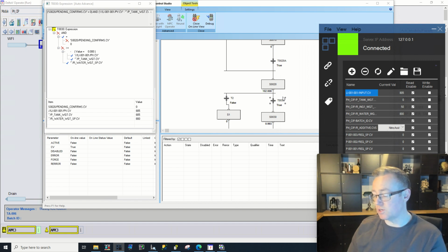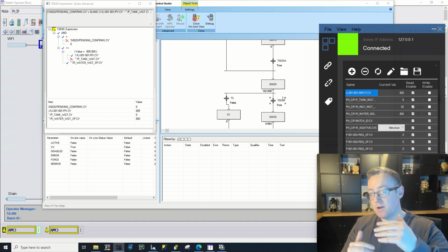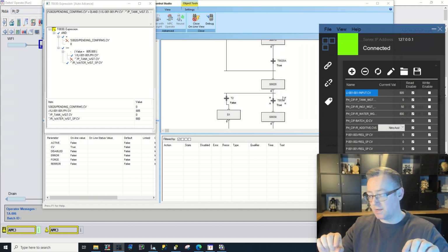And that's very much an example of how you call an equipment module from a phase, where there can be quite a bit going on in the equipment module. But the lovely thing about using it is that you can reuse it in different circumstances, especially in similar systems where you've got a large amount of logic that can be called all in one line when you're writing the phase recipe. Thank you very much.